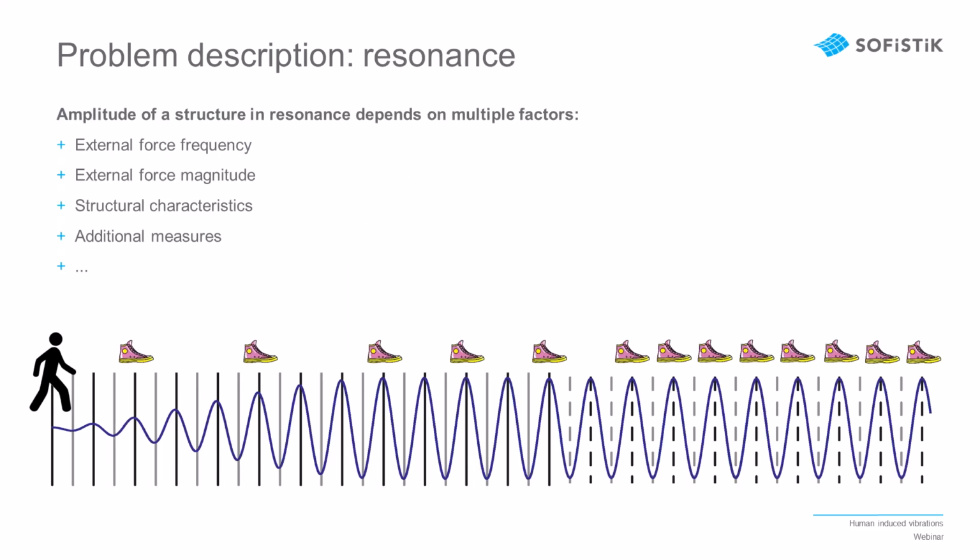So what is to be understood when we're talking about the resonance? A resonance occurs when a natural frequency of the structure matches the forcing frequency of the external loading or its multiple, as handsomely presented in the graphic at the bottom of the screen. This is an inherently dangerous scenario which can lead to excessive vibrations felt by the user, at the minimum breaching serviceability limit states, or it can lead to structural collapse at the maximum, which is an obvious ultimate limit state failure.